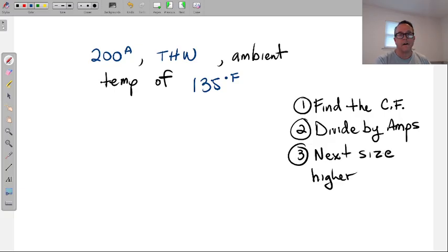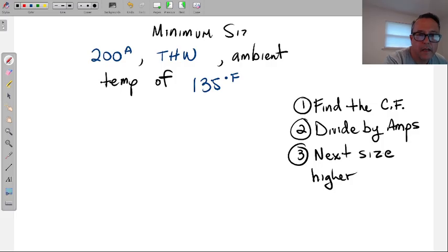All right, so remember the way this is going to get asked. What is the minimum, remember that, minimum size conductor we're looking for? Because you could always go bigger. You can always say, all right, that 400 kcmil, I'm just going to go with 600 kcmil. The code does allow us to go larger for the conductor as long as wherever you're about to terminate this wire can accommodate it. Which is why you can't run number 4 wire to an outlet for voltage drop, because it's not going to be able to handle it. All right, I'll pause here, and again, either direction you want to go, multiply to it or divide by it, and you're all set.